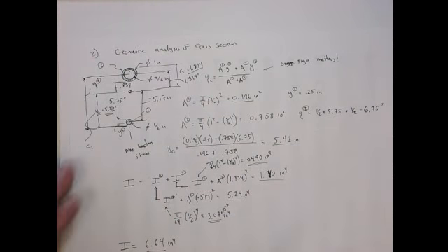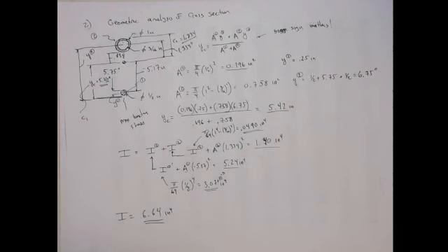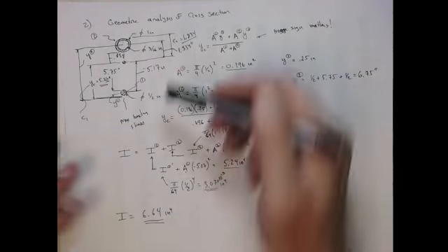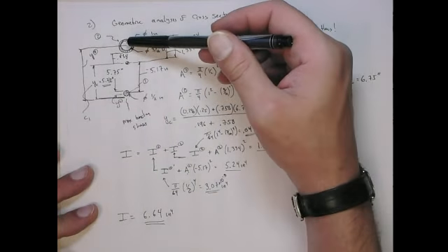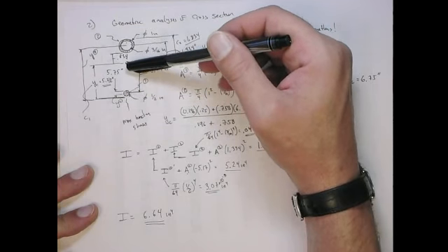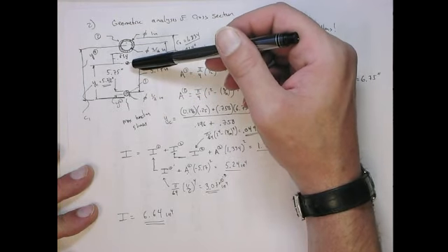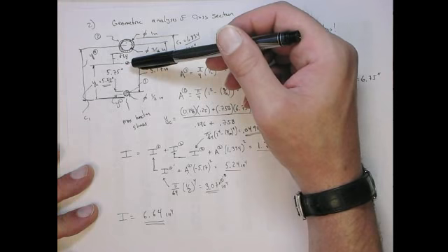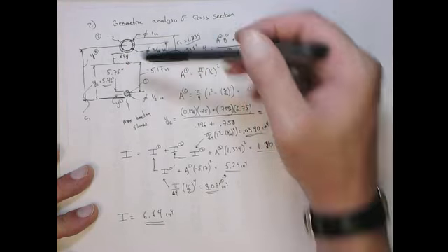So it has a significant effect. If nothing else, sometimes you can forget the details of doing these calculations. Maybe you can always go back in your books later in your career, but you always have to have ingrained in your psyche the fact that distributing mass or area farther away from the neutral axis is a more effective design for stiffening and stress reduction of a beam.